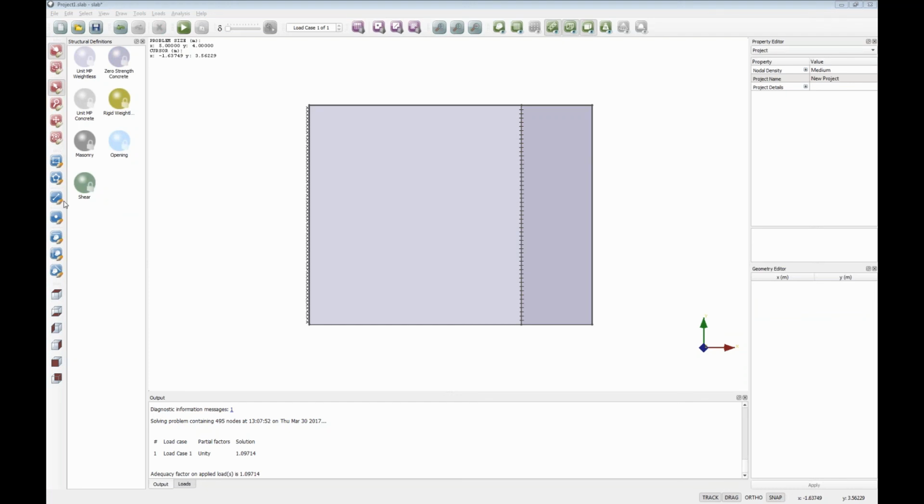Oh yeah, so as a follow-on to that one, they were saying, do we need to calculate the plastic moment capacity first and then add that in, rather than there being a way in the software to do it? And the answer is yes. So what you would do is look at the different sections of your building or bridge and then calculate the plastic moment and the direction accordingly and add that in as a structural definition.